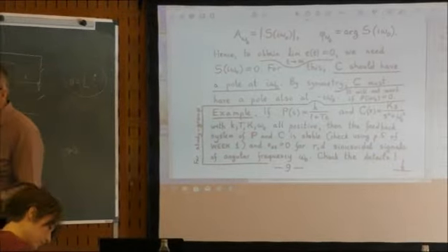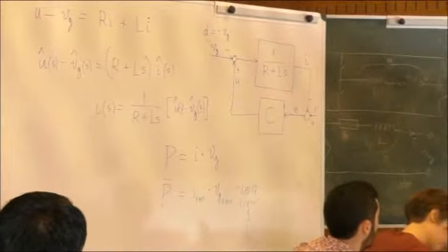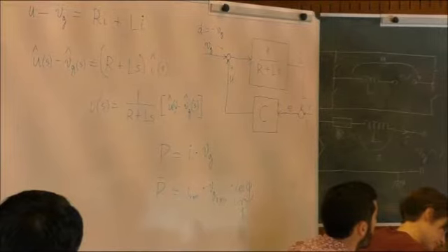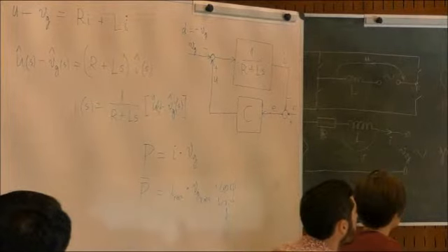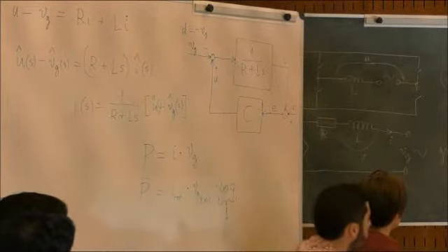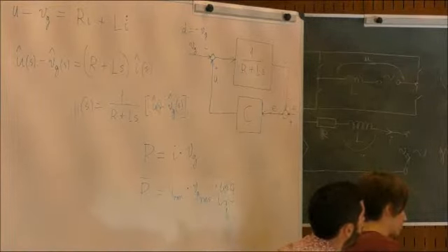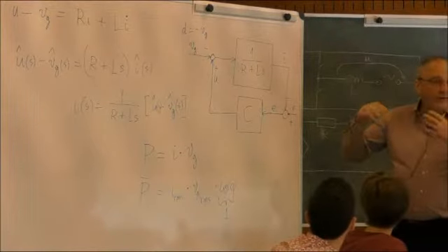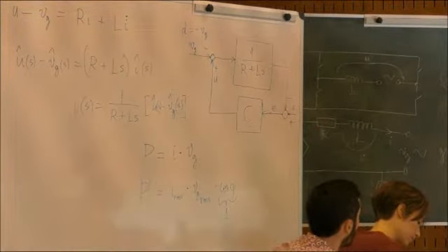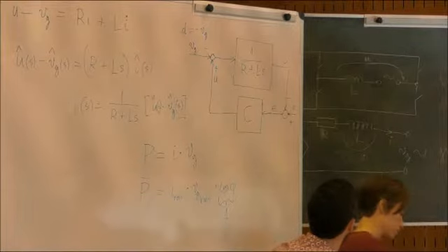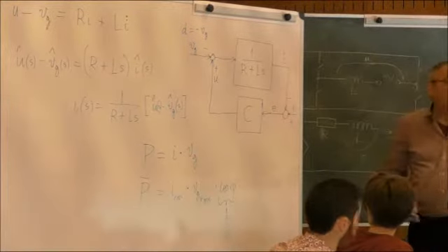Okay, so this power has to be this, but on the other hand, the power that I can extract from the solar panel on my roof depends on how strong the sun shines. So that depends on the hour of the day, and it depends on whether there are clouds or not. So that is something which changes. So I cannot fix a constant and say R is a fixed constant times Vg. That is not possible. I have to adjust it according to the intensity of the sunshine, because I have to achieve that this product should be exactly equal to what the solar panels can give.